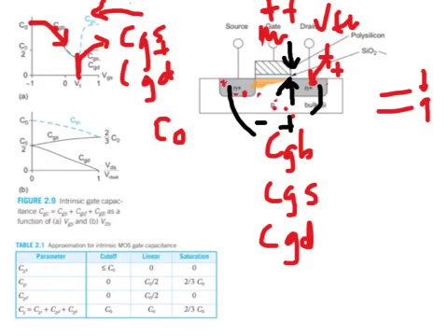So the capacitance between the gate and the drain would start dropping as a function of VDS, but because of this pinch off behavior here, the bulk of the capacitance linking this body of charge here with this body of charge here will be shifted to the gate to source side.